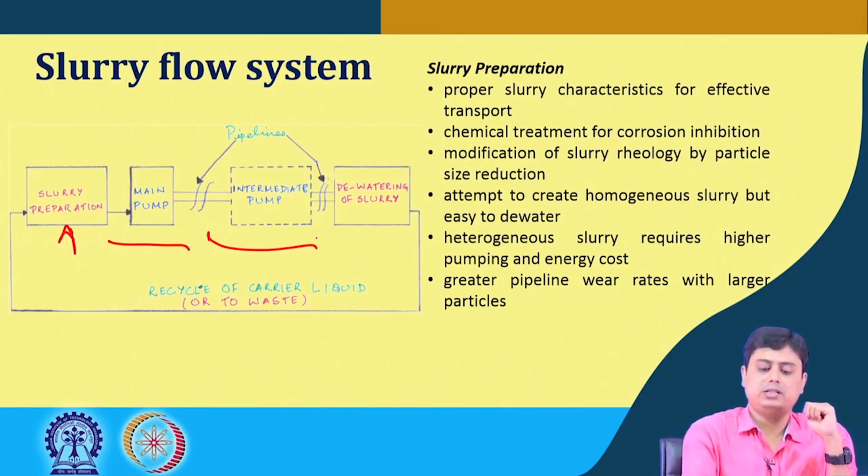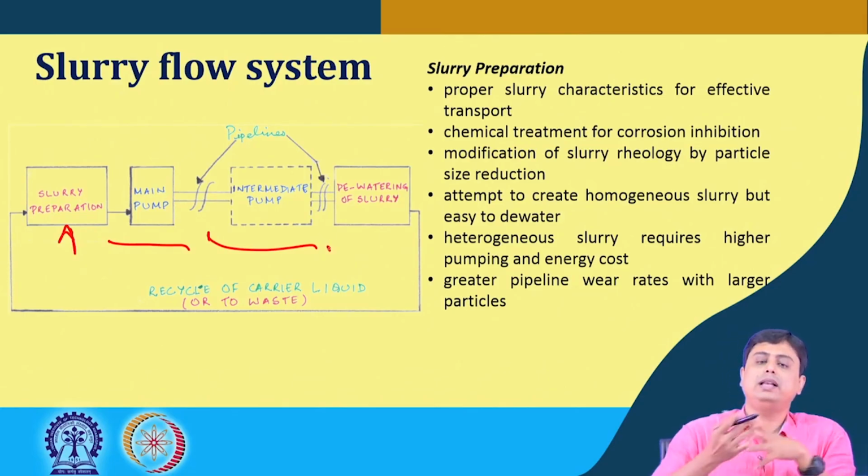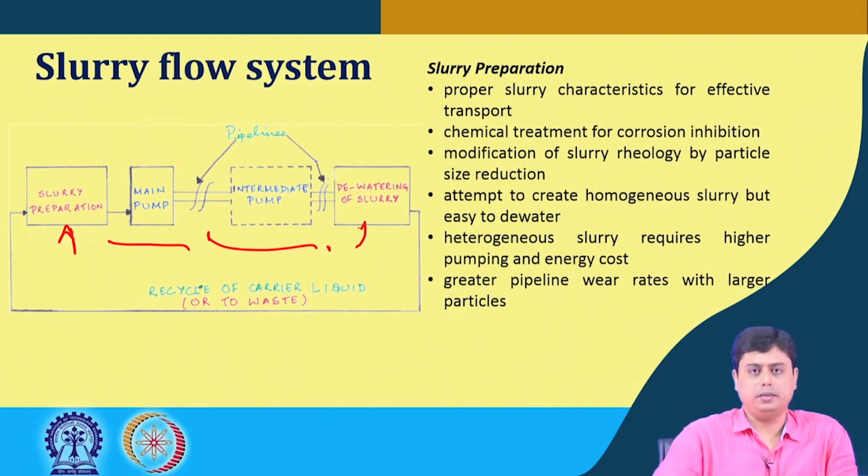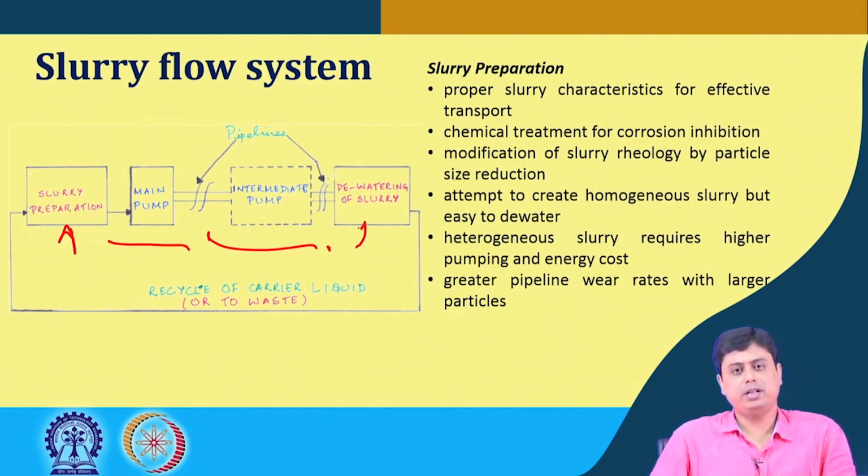And at the discharge end, once we collect the slurry, we have to recover the solid particles, because that is what we are carrying in terms of slurry. So, the step called dewatering of the slurry, because as I mentioned, most of the cases the slurry is prepared with water as the main component.